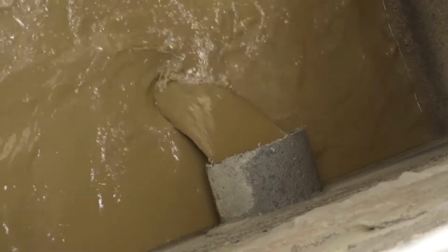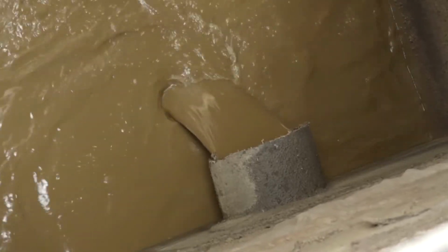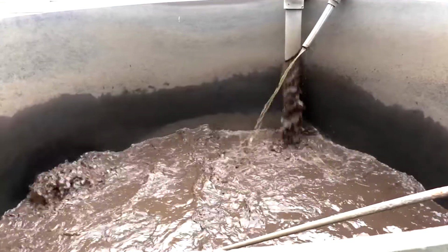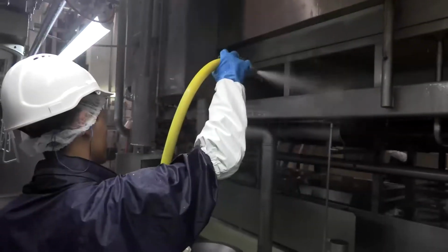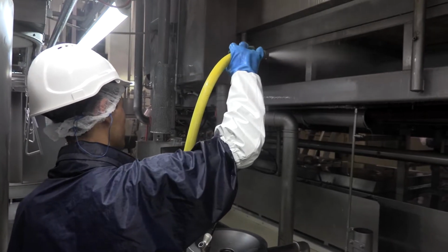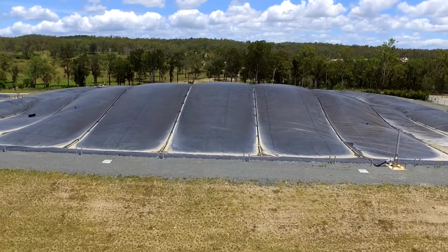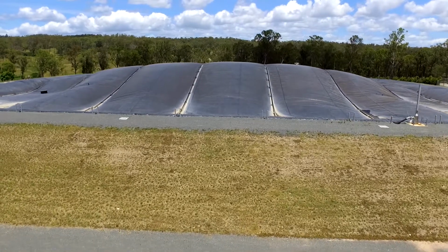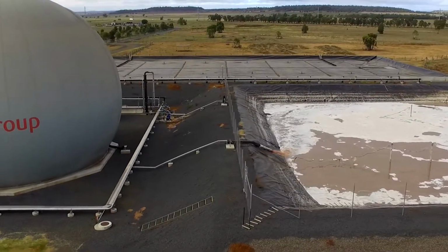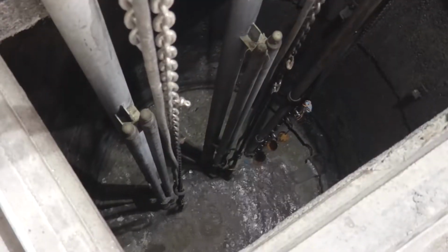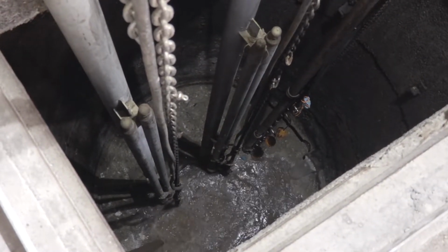A major challenge for most meat plants is the wide variation in wastewater flow during a 24-hour day. Typically, the largest flow occurs during the processing shifts when water consumption is at its maximum, especially when cleaning. For most meat plants with downstream anaerobic ponds, there is little need for balancing the wastewater flow, as the anaerobic pond acts as a very large balancing pond. In these cases, a save-all or wastewater pump pit is the only form of flow balancing.